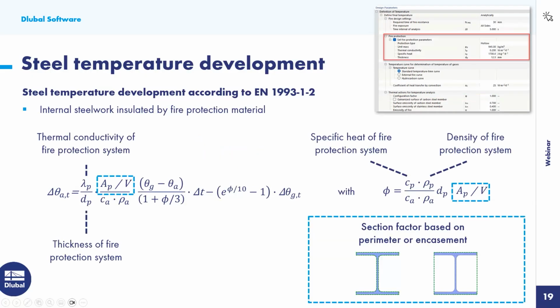So, as said earlier, the possibility to improve the fire resistance by galvanization is very interesting, as many steel structures are galvanized anyway for corrosion protection. And in this case, the improved fire protection is a nice bonus. But conventional fire protection systems exist as well. They have a much higher protective value, and they can also be taken into account in our program.